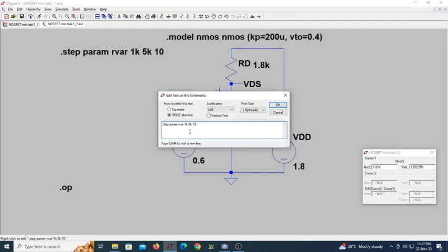The parameter you are changing is not RVAR but WVAR; you can give whatever name. Since we go up to 2222, let me vary from 1000 U to 3000 U with an increment of 10 U, so in this range I will come across 2222.